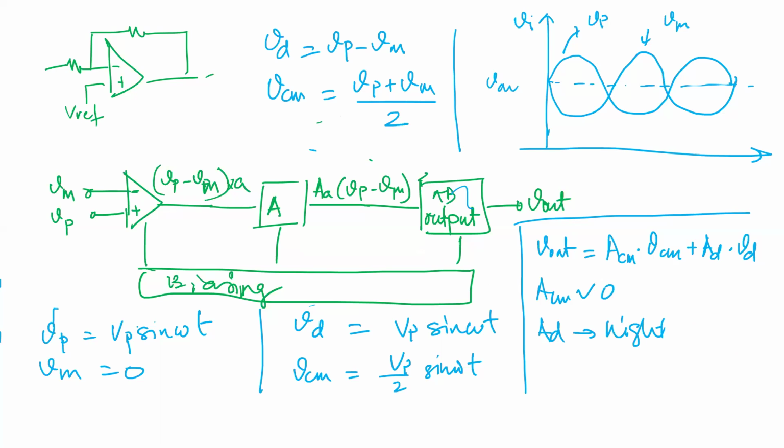So that's why when you put the feedback, this node gets close to this node. But any common mode, if these two nodes are moving together, then you don't want to amplify that. And that also helps you with noise, because let's say you have a supply noise. Just like before, you have some cap which couples to both nodes. That will come out as V noise on Vp and V noise on Vm. You add them up, divide by 2 times ACM, it will become 0.